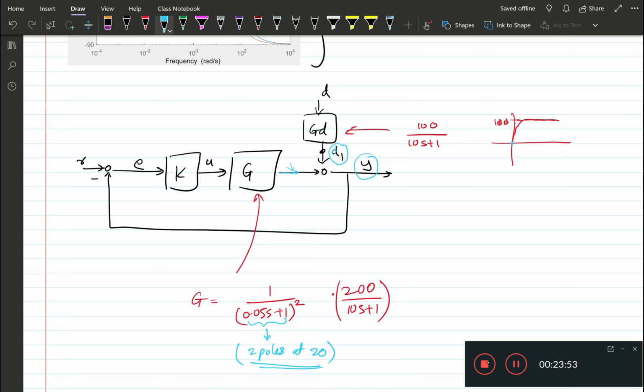So that's one possible explanation of why it is extremely difficult to not have the overshoot when we have a reference step input, where at the same time we satisfy the disturbance rejection requirements, which are keeping the output y between -1 and 1, rejecting it quickly, and having the control input at all times between -1 and 1.